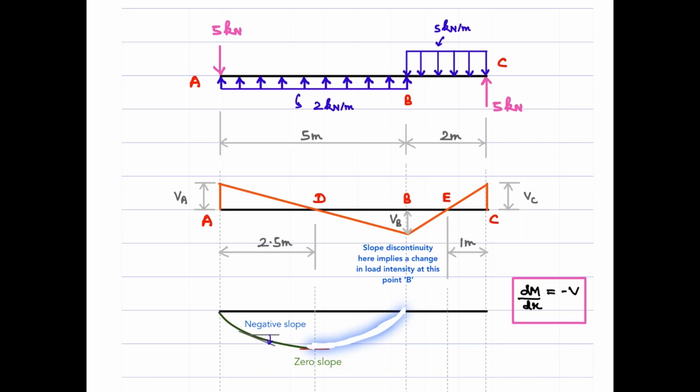Okay. So for this span, it has to be like this. Only then it starts with a 0 value, and you see that this is a positive slope for us. So maximum positive value, and then when we attach a negative sign to it, it is going to represent the maximum negative ordinate attained here. Okay. And then for this span, it has to go like this. Okay. So it becomes 0 here. The slope is 0 here, which means the ordinate of shear force is 0 here. And this is a positive value. Okay. If the trend is like this, we will have a positive slope here. And then if you attach a negative sign, it will correspond to the negative ordinates here. So that's the logic here.